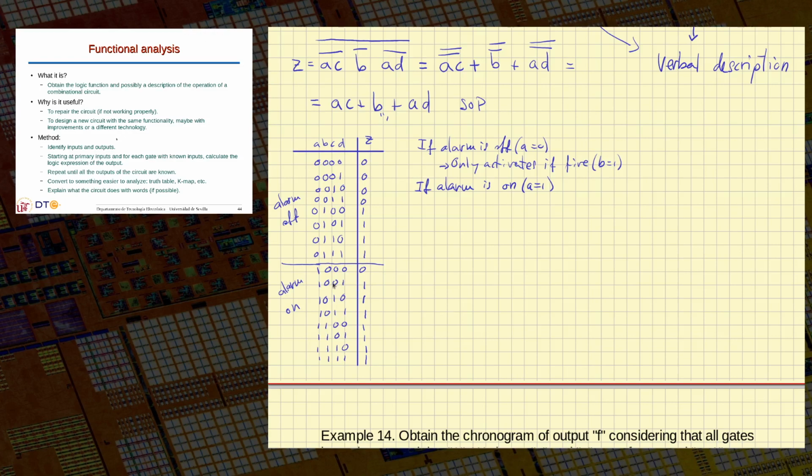So it will ring whenever I remember C is the door detector, D is the presence detector. So if the alarm detects anything, presence, door opening, or fire as well, the alarm will ring. The alarm will not ring only when there's no emergency condition. When the door is closed, there's no presence, and there's no fire. This is the normal state when I leave home. I connect the alarm, there's nothing strange, so the alarm is deactivated. Okay, if there's any condition in any sensor, it will ring.